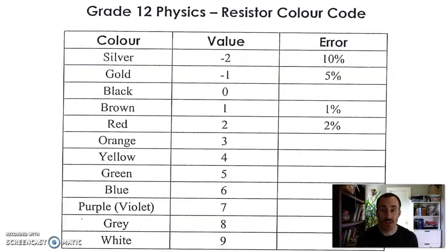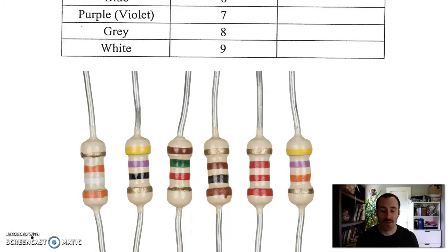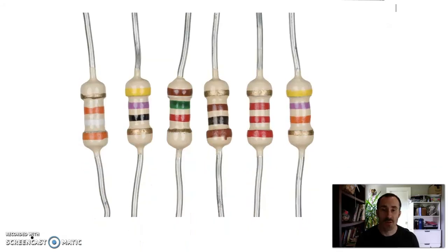Now, if you're following along in the notes, there's also this section about resistor color coding. We're not going to worry too much about that part, but I do want to show you how it works. Here are some resistors. This is what they look like. Not all resistors look like this; there are different classes of resistors that all look different. But this type uses colored bands to show what resistance they are, which is helpful if you're building your own circuit. You should probably know what the resistors are when you're putting them in. They have 4 colored bands. Let's look at this one, for instance.